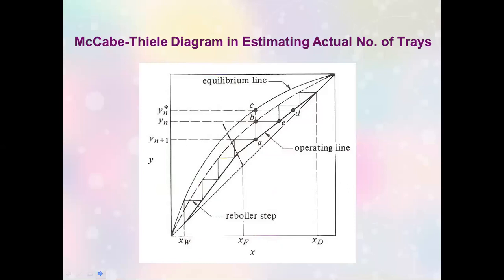Now, the thing with using efficiencies: where do you often encounter this Murphree efficiency, and how is it being introduced in the problem, or how will a problem be created out of this concept? If you use the Murphree efficiency that is given in the problem, the usual way of solving for what is required, most of the time something to do with the actual number of stages, is done graphically. So I will explain it in the simplest way possible here.